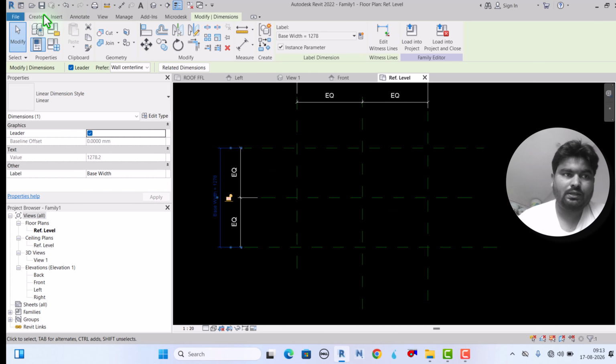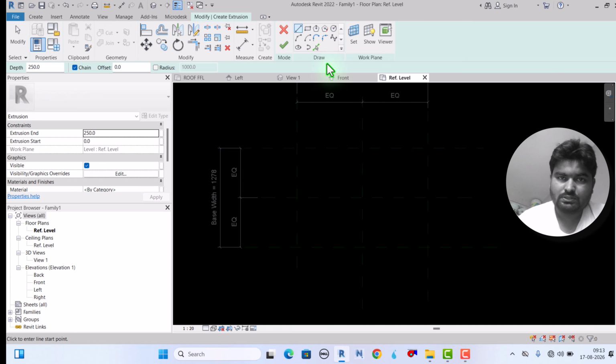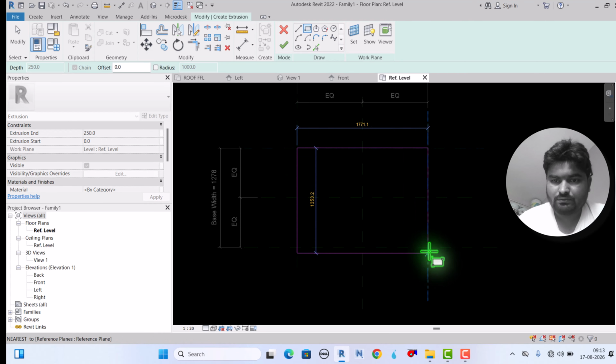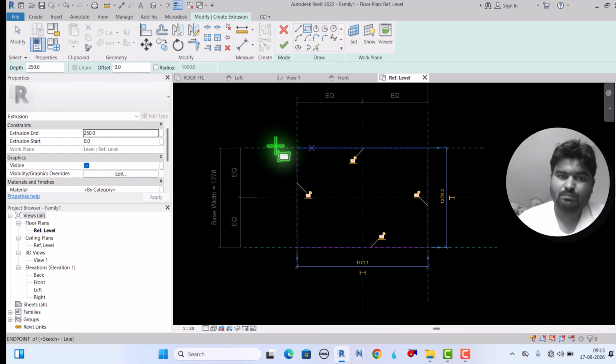Okay, now I have to create our base. It is like this. We can select the rectangle, and draw it here and from here, right? And all four of these I want to lock. Why? Because I want that when the reference plane moves either way, then our object, this geometry, should move according to the plane.